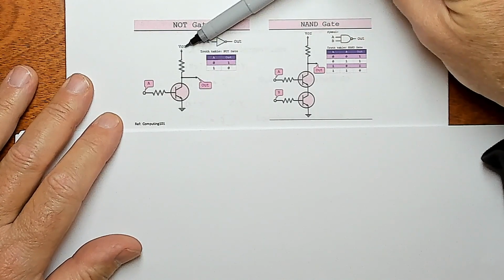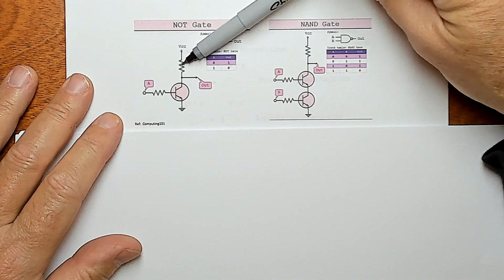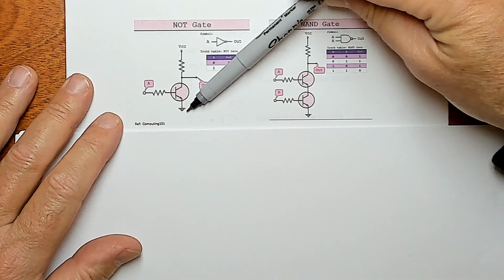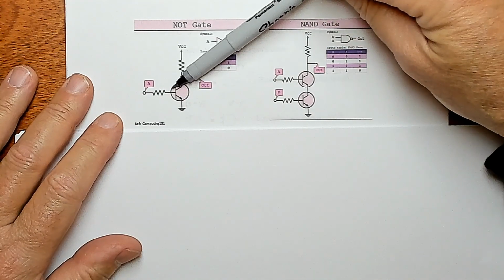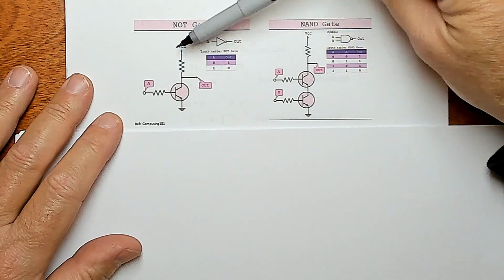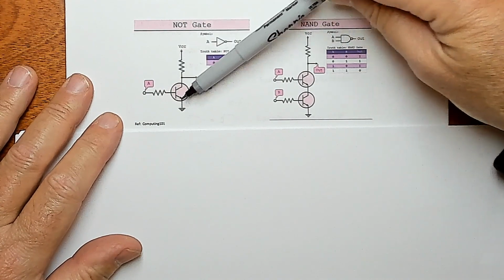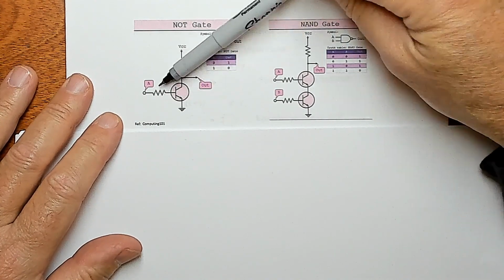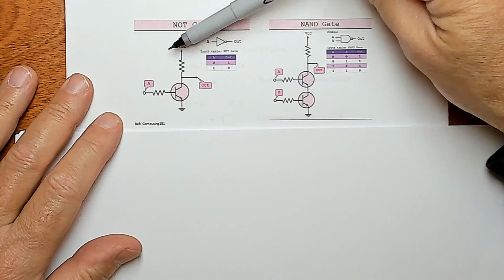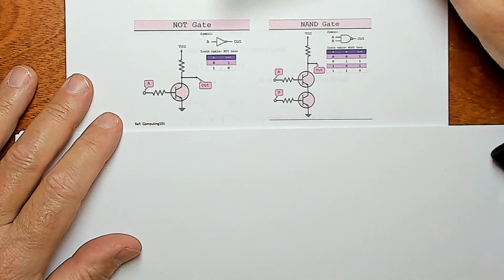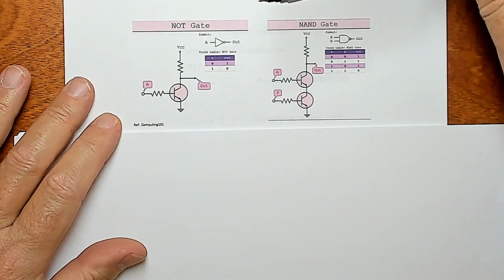So there's a voltage here that can either come out or go down the drain, one of the two. So if you close the switch by putting a 1 on here, then the 1 that's over here will go down the drain instead of out. So you'll see a 0 here. So you put a 1 on here, you see a 0. You put a 0 on here, this thing is open and the 1 comes out. So it does the truth table.